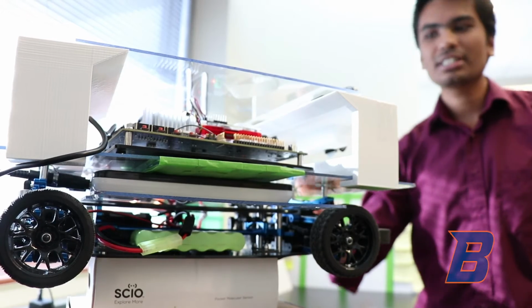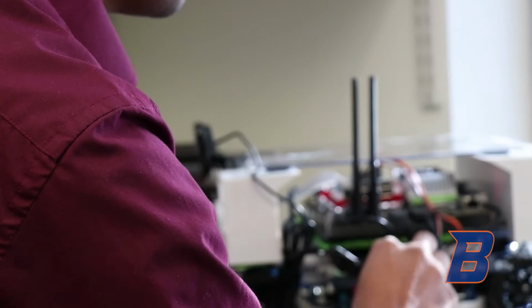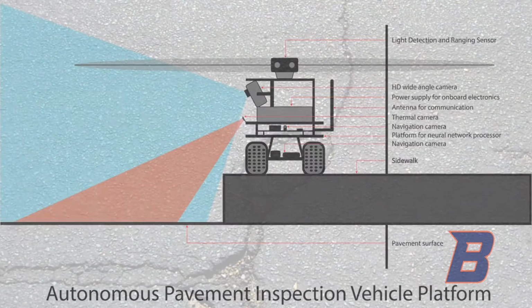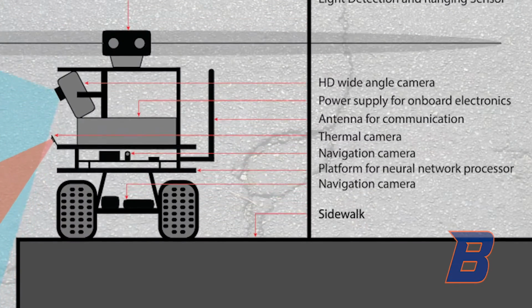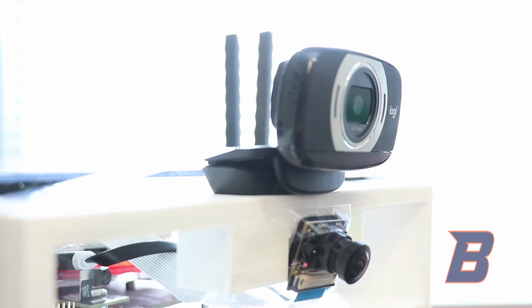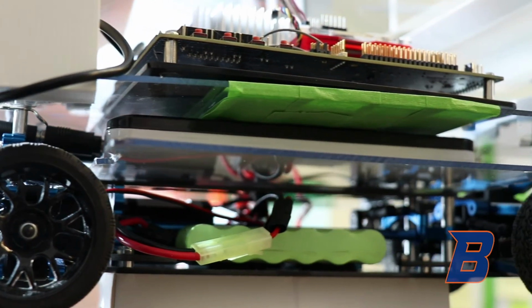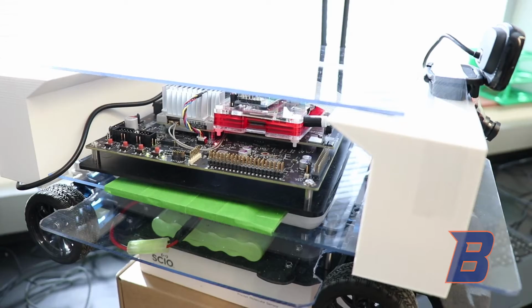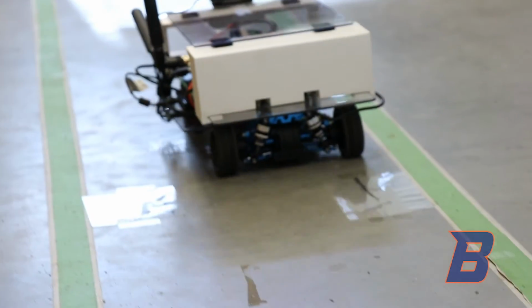The current ongoing autonomous driving vehicle is the platform that I'm really proud of. The initial goal to design this platform is to test and develop the AI model. We thought there should be a better way than manually measuring all the cracks on the road. We took an RC car and modified its upper portion. We picked NVIDIA's Jetson board and Raspberry Pis for 2 different systems. One system does the automated driving part and the other does the detection part. They can automatically analyze the data and send it to a web server so that we can monitor the whole road system.